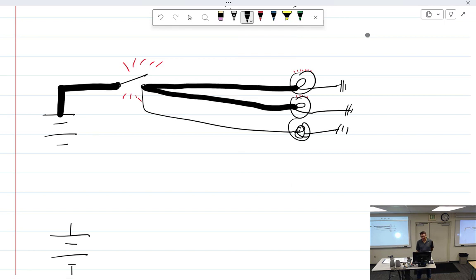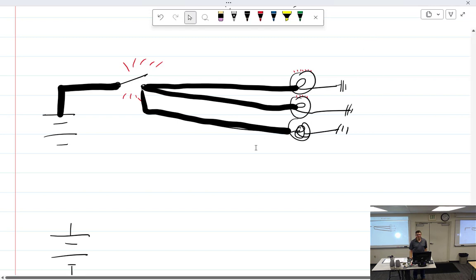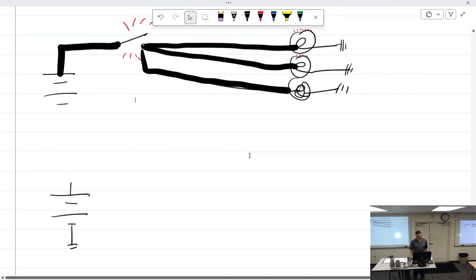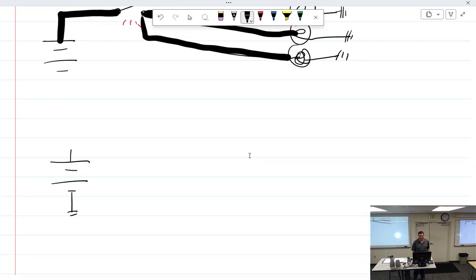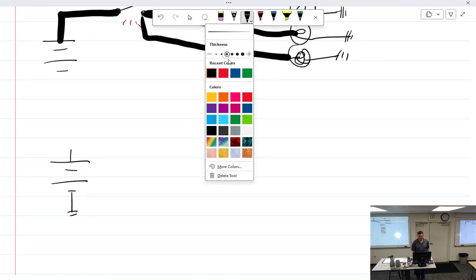No. So what two mistakes do I have going on there? Ground wires. Oh, it's just a ground wire. What, it's to keep me from getting shocked? No, all of the power is literally coming in this way through a teeny tiny wire, then through this, then through a nice big fat wire, then back to the teeny tiny little switch. Did anything change? Nothing changed. You could flip the switch and you'll just never open it again. Yeah, the switch was welded closed.